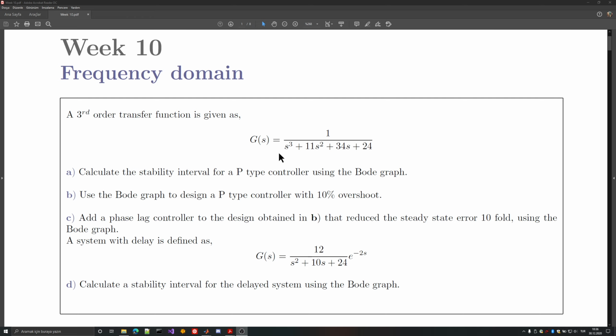So it will basically be very interesting to use the Bode plot or the frequency domain, because it has some mathematical beauty to it. Because, for example, you can take the inverse of the system, but the Bode plot will change so that the low frequency and high frequency behavior will be interchanged, because 1 divided by omega and omega have an inverse relation. So the high frequency becomes low frequency, the low frequency becomes high frequency. So that way, basically, it's an interesting method to use frequency domain approaches.